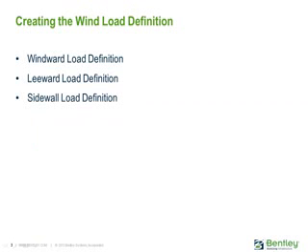For this video, we'll be focusing on creating the wind load definition, which will be the first step in incorporating our wind loads into our STAAD.Pro model. STAAD.Pro does have the ability to generate wind loads based on a number of different codes and reference standards, and then apply these to a variety of structure types. Pressure distributions are calculated and converted into forces, which are then applied to the structure as nodal loads. To create our wind load definition, we will create a separate load definition item for the windward, leeward, and sidewall loads for each global axis direction.